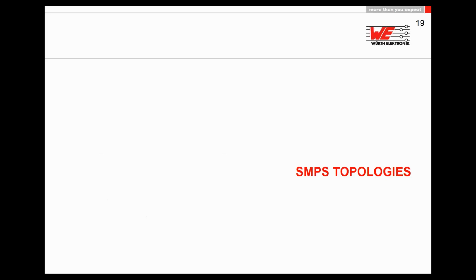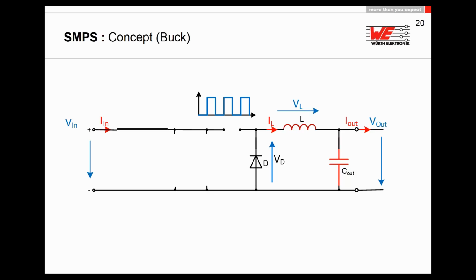Now, if you talk about switched mode power supplies, let me talk first about the buck converter. The buck converter, in the first step, you can consider like an LC filter. You apply a rectangle signal to this LC filter and you're expecting a DC voltage on the output. Well, the problem is that the world is not so nice like we imagine and we dream. If you apply a rectangle signal to this LC, it will reflect noise. And for this noise, you will need to put something like a ripple capacitor on the input to try to filter out this reflected noise.